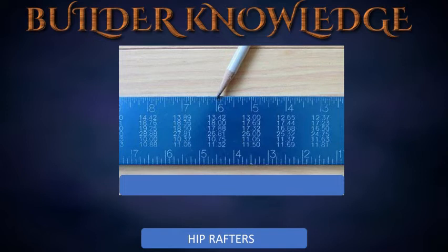Look below the number 6 at the top of the framing square. The second line gives 18 inches as the length of hip or valley run. Multiply the length of hip per foot run by the total run. 18 inches by 14 feet equals 252 inches, or 21 feet 0 inches.